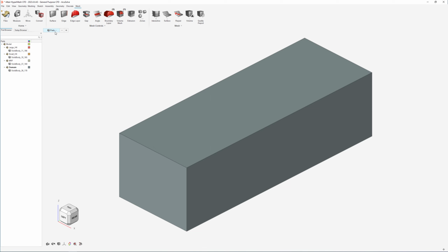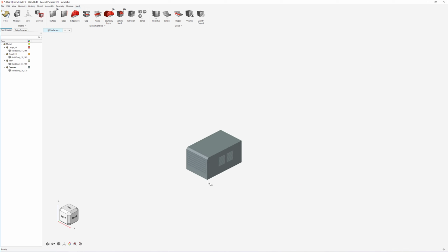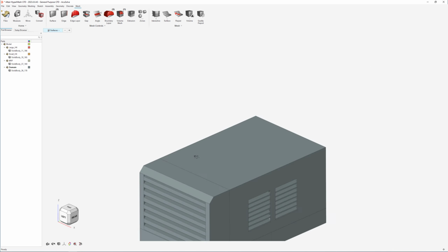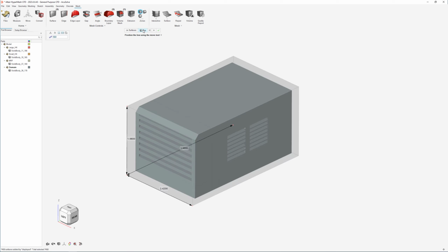The last step is to create some refinement regions around the canopy to achieve a high density mesh inside of it and a smooth size transition to the larger elements of the far-field domain. From the zones command, I'll select the box mesh zone option and I will click on the box button in the guide bar, leaving the dimensions as default. The average element size will be set to 0.02 meters.